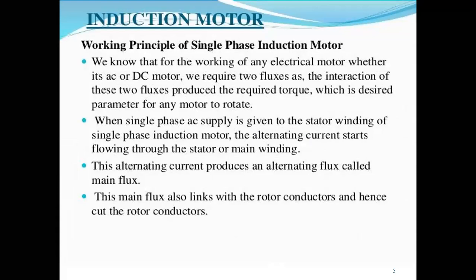There are lots of applications of the induction motor over a DC motor because it has low cost. It requires less maintenance. It is simple in construction. It is reliable. Its power factor is also good, and we can call the induction motor self-starting because it does not depend on any other device. That's why we can say it has lots of advantages over the DC motor. So here we will see firstly how the single phase induction motor works.